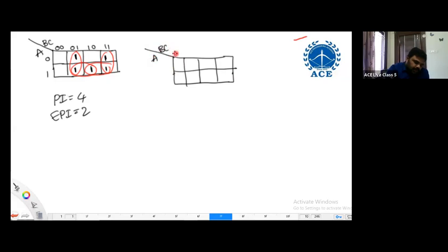A, B, C: 0, 0, 0, 1. Next 1, 1, 1, 0. It is 0, 1. Then what can we get here? These are the minterms. If you swap the 1, 0 and 1, 1 columns, this will be the K-map. I hope no one is having doubt why we have swapped the columns. An intentionally wrong K-map was given. That is the reason I'm adjusting this K-map.